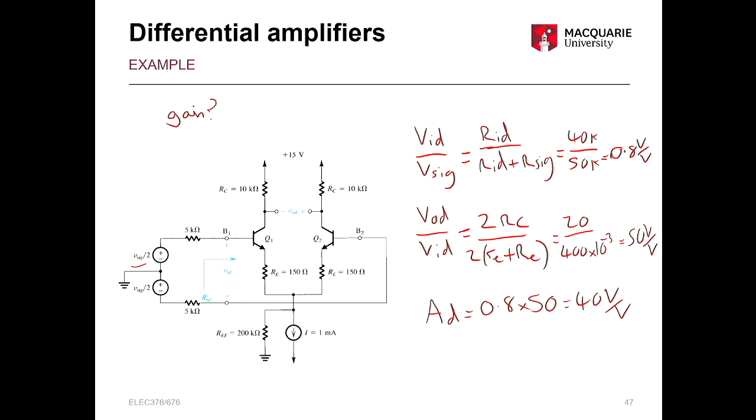Oh, sorry, yes. No, 2RC in this case, sorry, 2RC, because it's our total from the collector. This is 2RC. Yeah. So this one's a complicated example. I suggest this one's in the book as well, which goes through it a little bit more with a few more steps and explains a bit more about how we can use these ratios, okay? But the idea is it's the total resistance seen by the collector terminal, so you add them up.